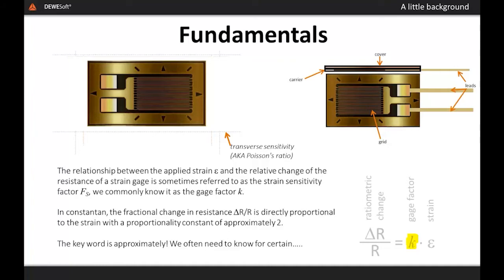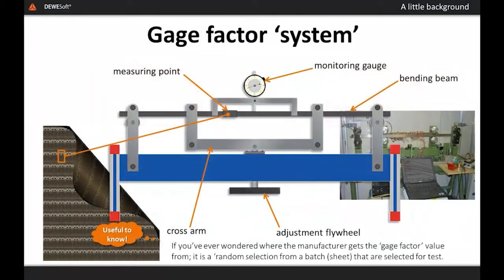As mentioned before, the testing is determined by randomly selecting gauges from the sheets or batches. These are literally mounted as you mount any gauge in normal use onto a very controlled test beam. In the image, you can see a large number of gauges mounted on the beam in the background. Another step in this process that is very labour intensive is the cleaning off of all the gauges from the test beam, and this has to be performed extremely carefully using non-destructive methods to preserve the integrity of the beam and the material and geometry of the beam.